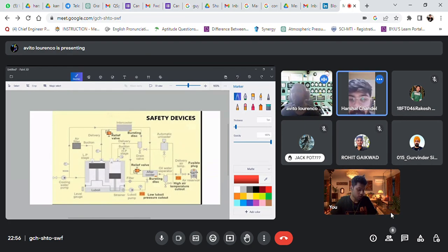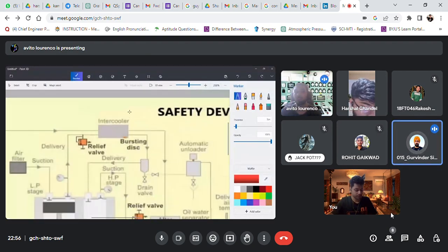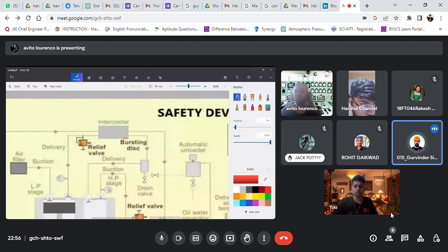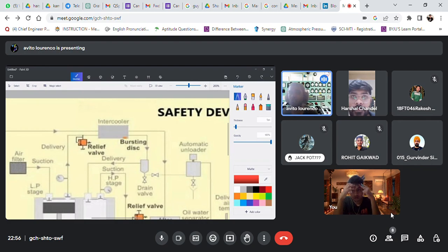Cooling water? Not necessarily, no. I think in, let's say, for example, in the Dreamer package he said high water temperature, jacket water temperature. I guess it's jacket water, because the issue I'm having is if I say no flow in the cooling water, it could be that my feed pump is off. It should not give a false reading suddenly saying the bursting disc is exploded, people will start running, what the hell has happened to the main air compressor.